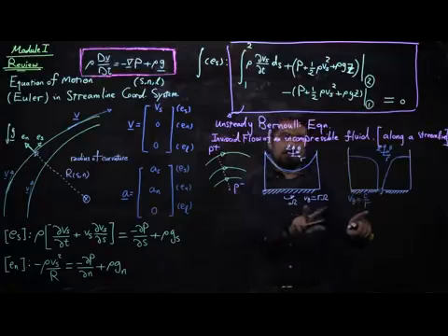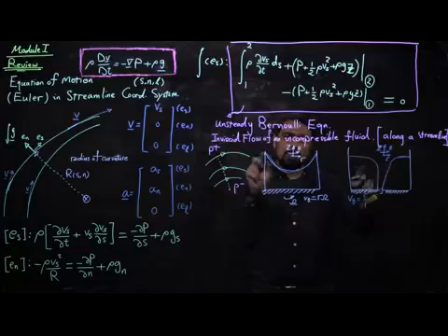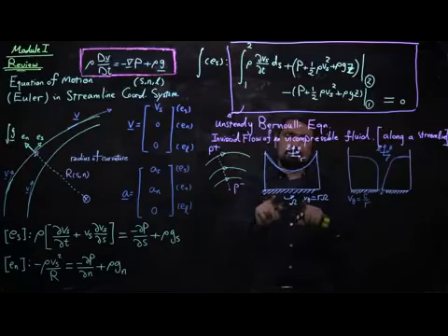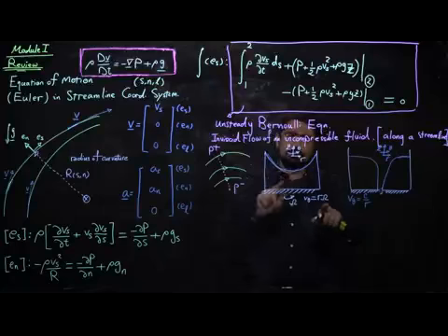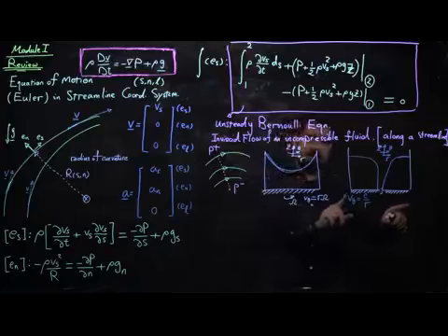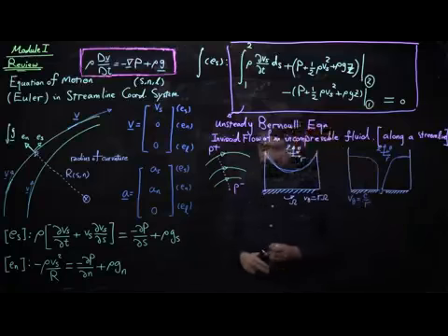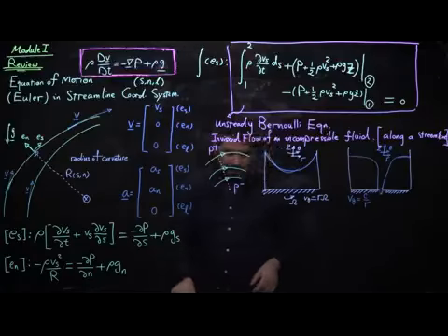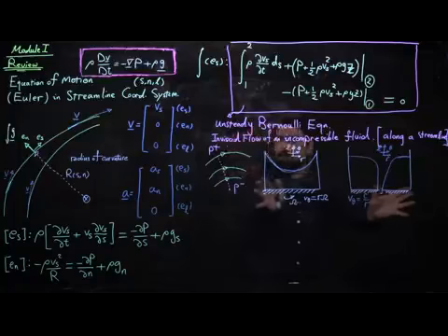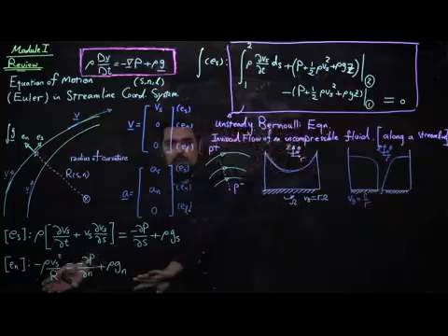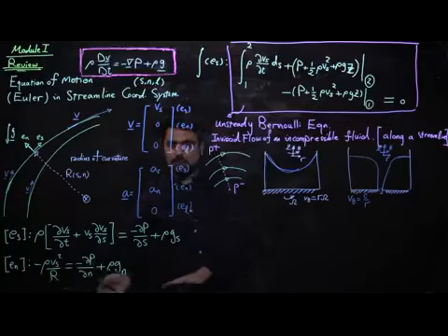But since the kinematics and the change in velocity is dramatically different between the two, the parabolic equation that you see for the profile in rigid body rotation does not repeat itself for the ideal vortex or the drainage problem. And you get a different profile, which we studied extensively. Now, these were nice applications of Euler equation normal to streamlines.